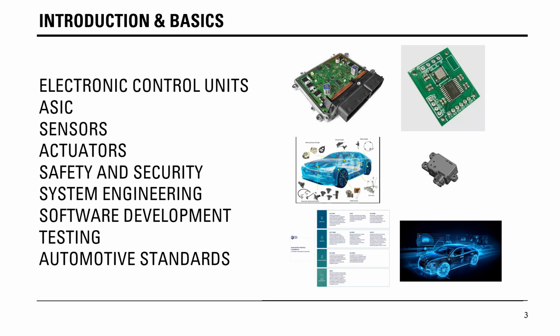And this has been divided into an application layer, basic software layer, microcontroller layer, and hardware abstraction layer. This also has a quite close relation with the OSI layers of the standard ISO. And then this has been evolved later, from basic AutoSAR to adaptive AutoSAR, where we have more enhanced features in terms of software configuration, integration, development, and reusability of the components. We will discuss these details in upcoming videos based on each topic.